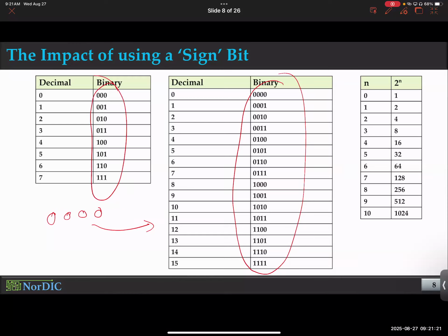So by getting rid of one digit as just the sign bit, you're basically getting from this 16 options to just 8 options. So essentially, in a 4-bit number system, if you use one bit as a sign bit, the other 3 could only give you 8 numbers. You can only have 0 up to 7, that's all. And -7, like that's the cost.